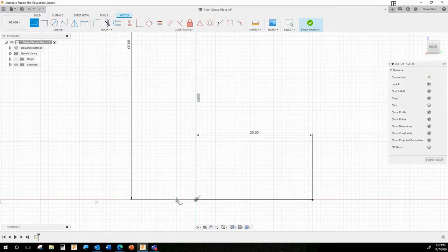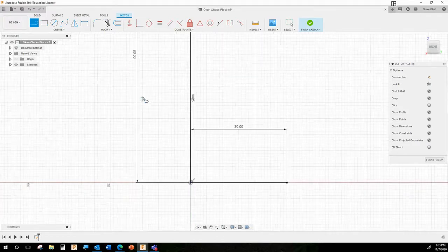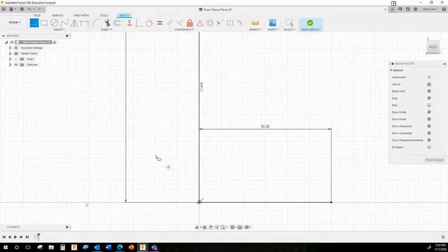It can be as far over, as close as you want. You're just going to put it somewhere convenient. And by the way, the software created these itself when I drew these lines, because I didn't hold the mouse button down. But for an arc, it's not going to do that. So for lines, you don't really need to go and create special lines. It automatically creates them. Same for rectangles. Mostly you're going to be doing this for curved things.